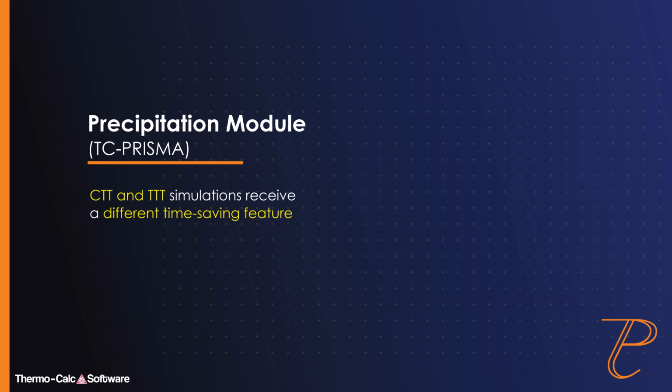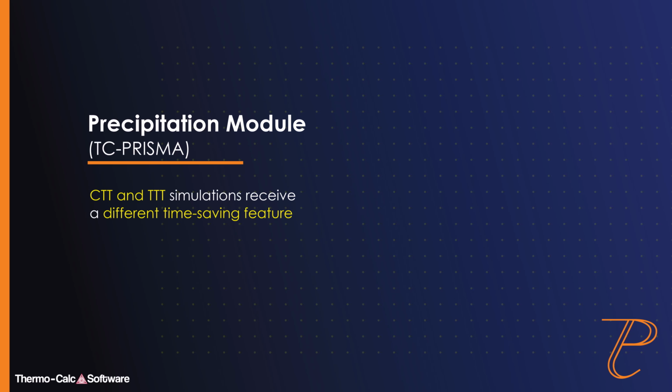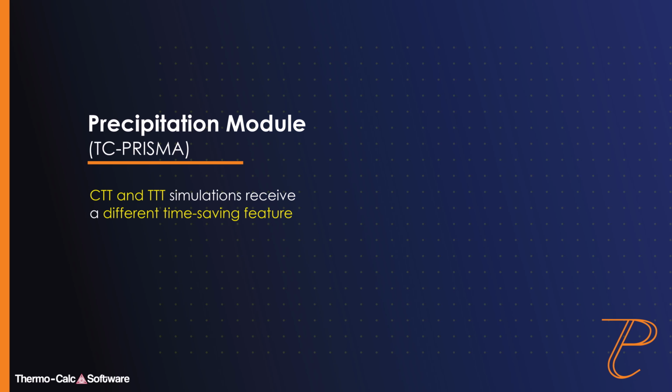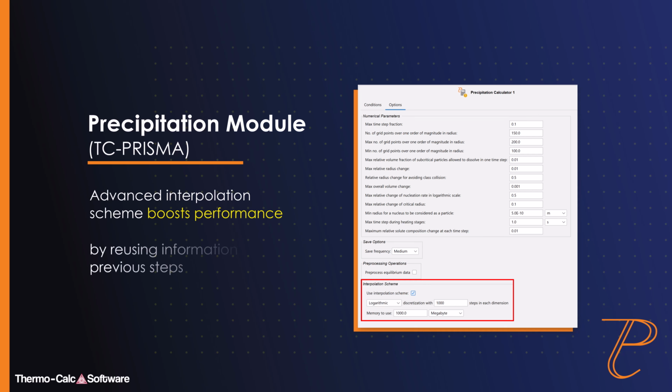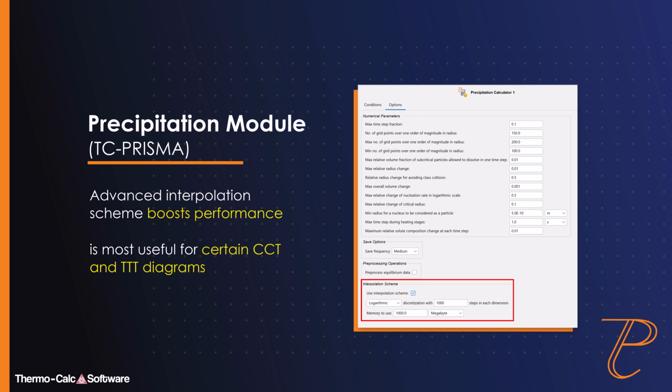However, CCT and TTT simulations receive a different time-saving feature. A new advanced interpolation scheme boosts the performance of simulations by reusing information from previous steps. This is most useful for certain CCT and TTT diagrams.